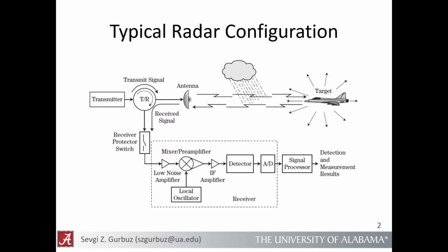And once you get your received signal, you'll usually have some hardware on the received end, which is geared around trying to isolate and eliminate sources of noise. Usually you have filters so that you're only receiving and preserving the signal around your bandwidth of interest. And then eventually you digitize your signal and it goes to some signal processing unit, which can either be an edge computing device or it can be your laptop or something of that nature.